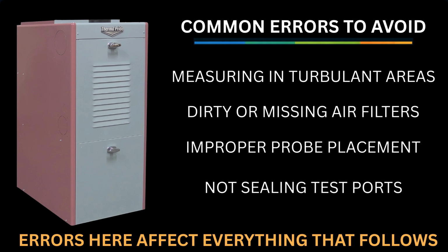Common errors to avoid: measuring in turbulent airflow zones, dirty or missing filters, improper probe placement, not sealing test ports. Accurate measurement is critical. Errors here affect everything that follows.